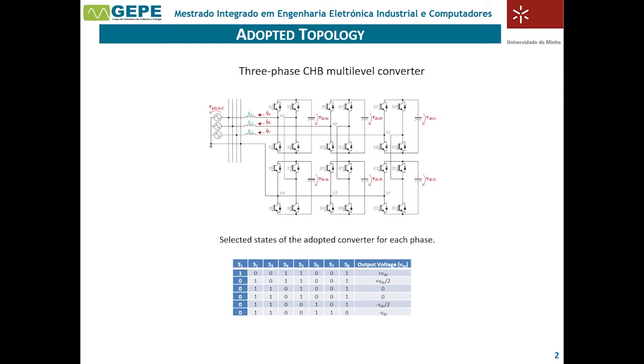Considering that there are two independent DC links per converter, 2 P controllers are implemented, one for each DC link. Each of them works either in the positive semi-cycle or in the negative semi-cycle of the grid voltage.